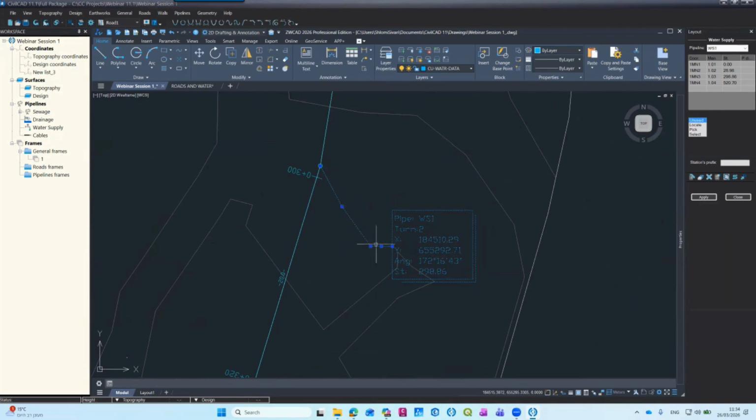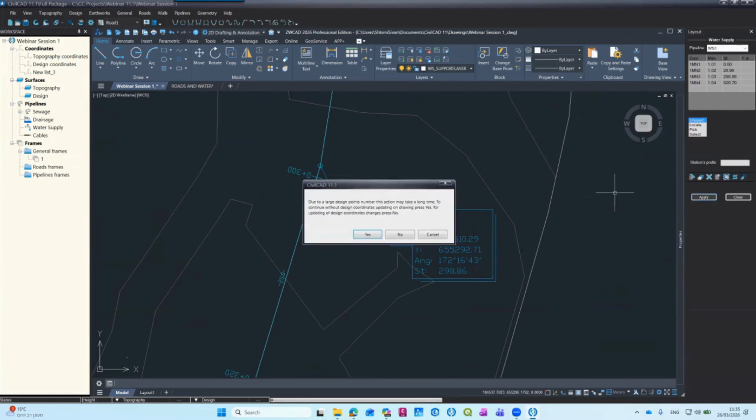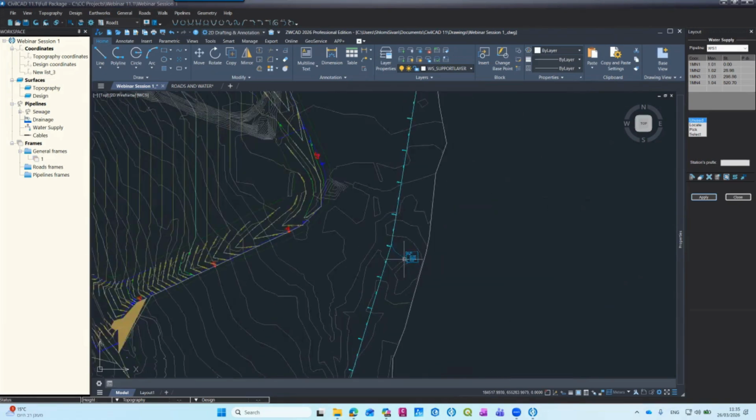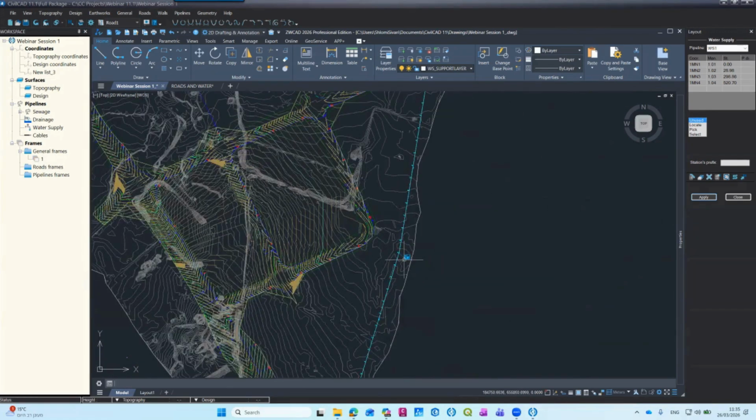So I can do like this, do like this. By the way, the system will now remember the location of where you put your M leaders. So even if I apply, in the past, it used to redraw. Now, no, it will remember the location of the M leader. Okay, keeps its location. So this is a nice feature that we already have.